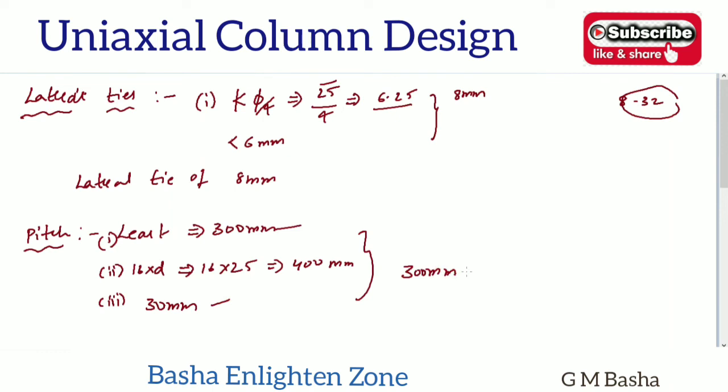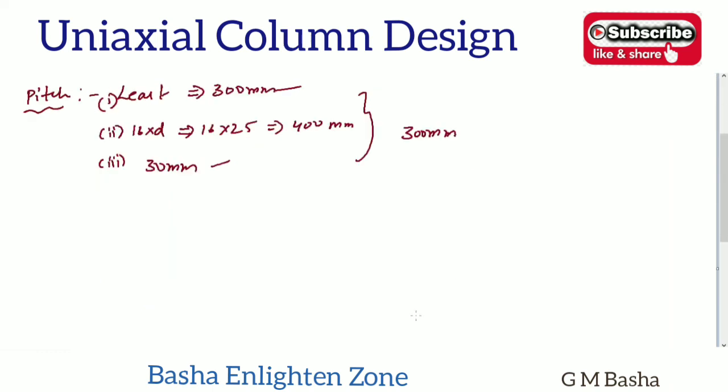Therefore provide the lateral tie of 8 mm dia bar with 300 mm pitch. So this is the procedure for finding the lateral tie and pitch.